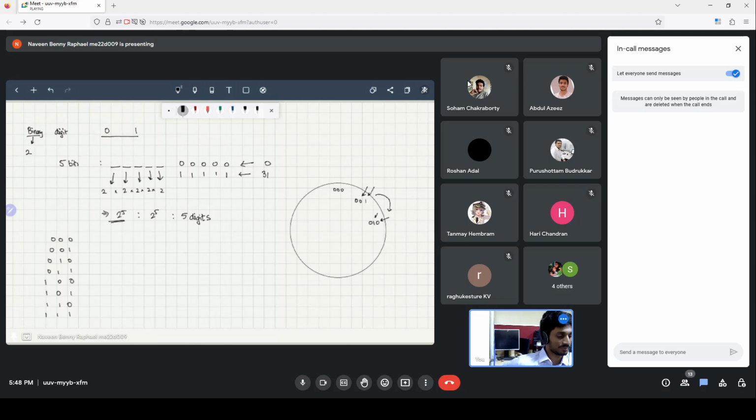This is not good, because as I explained earlier, while you're reading this, the wheel moves. So you will read one digit from one and the other digit from the other, and in this case it could be read as 0, 1, 1. Okay, 0, 1, 1 is not a big issue. Or you could read this as 0, 0, 0, which is also not that bad. But the earlier example was much more dramatic. Like when 0, 0, 0 changed to 1, 1, 1, it becomes 1, 0, 0, which is all the other end.